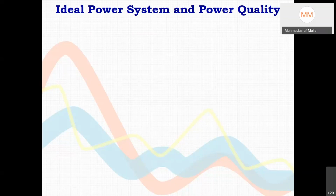Now the fundamental component of this current might be in phase with voltage. But if we try to match volt amperes, that is the RMS current we are drawing through the conductor, and the wattage, the power the load is getting, suppose it is a rectifier, so the DC side power, once again it will not match.